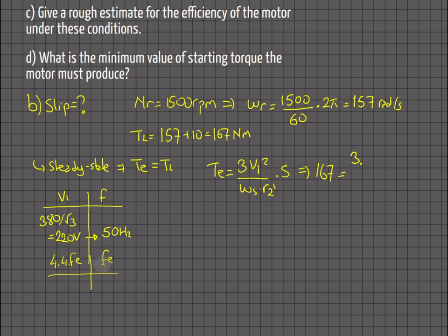Okay, if I increase the frequency, I should increase the voltage. If I reduce the frequency, I should reduce the voltage. And if I write everything in terms of omega s, so omega s is the actual mechanical synchronous speed. I'm not talking about the electrical one because I will use it in the torque expression.